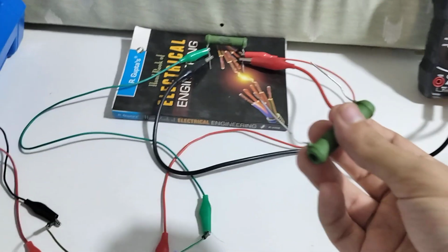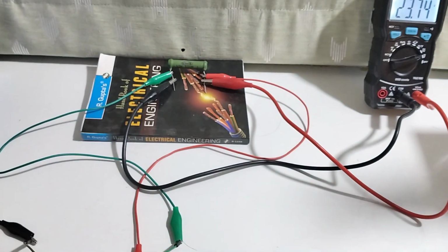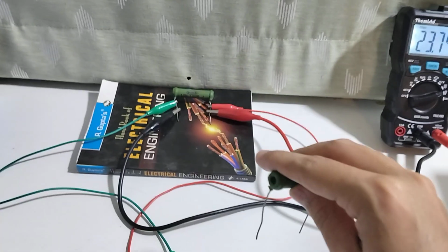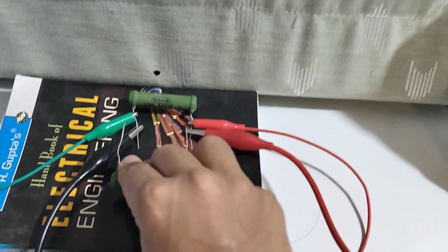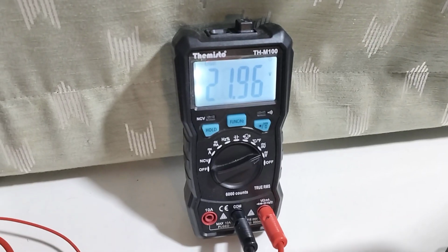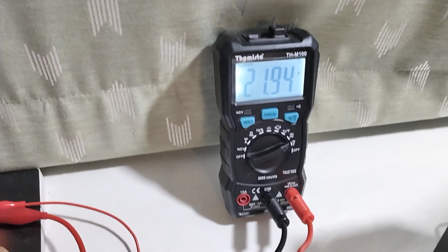Normally if you had an open loop controller, that would just bring your voltage down immediately, even below 20 volts, because at the same duty cycle it can't handle that much load. Now since we have a closed loop, I'll just touch this here, and you can see our voltage drops to 22, which is still within roughly 2 volts of our actual 24 volts.